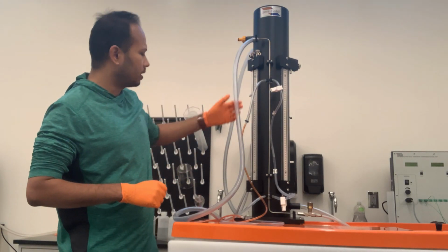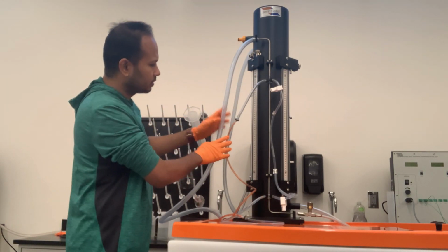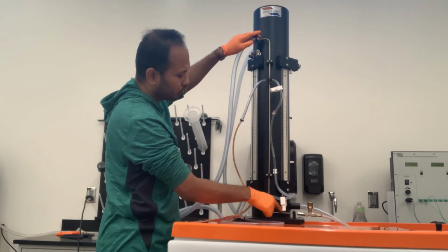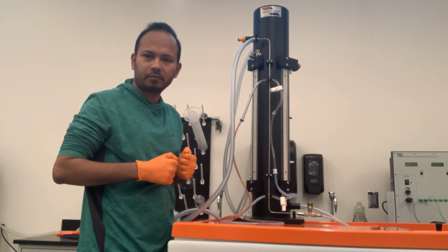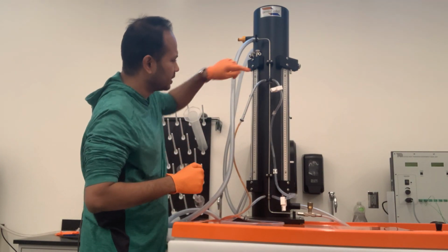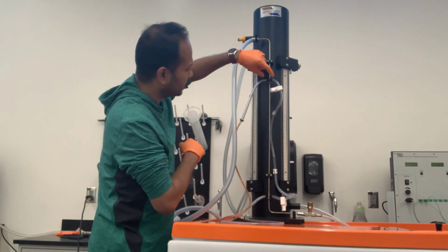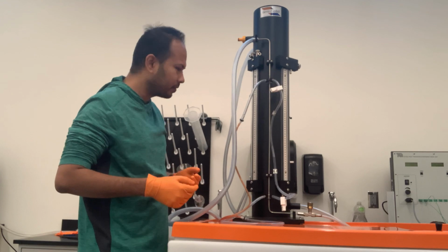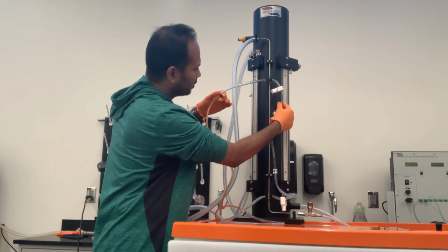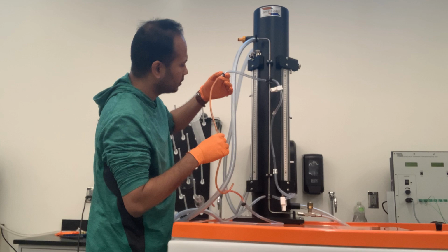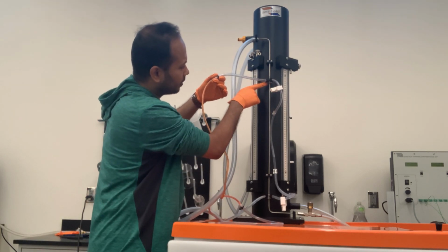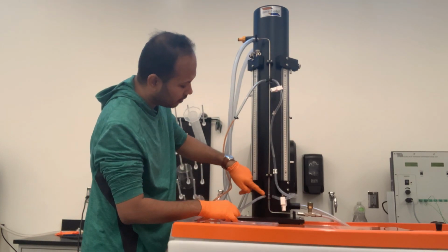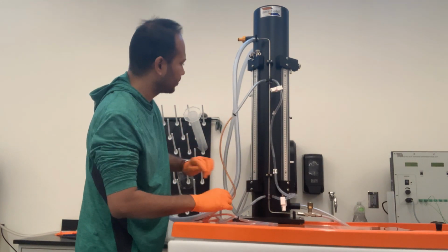So this is the inlet, and this pipe you see is a smooth pipe, 3 millimeter in diameter. We are measuring pressure from here to there, so this length is half a meter. These taps connect to measure the pressure at this point, and there is another point here to measure the pressure almost near the outlet of the pipe.